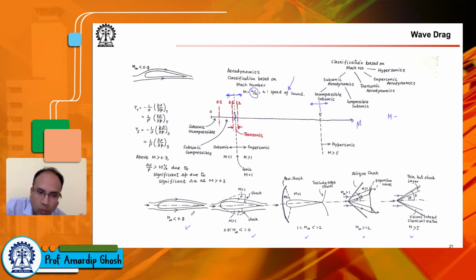Generally, if you're flying close to Mach 1, but less than Mach 1, so subsonic still, your flow field around the wing, although it accelerates on the top, and you can have local areas of Mach number 0.85, 0.89. What we are saying here is the Mach number is sufficiently less than some critical Mach number, because of which, although the flow becomes greater than 0.8 here and there, the flow never becomes sonic or supersonic.